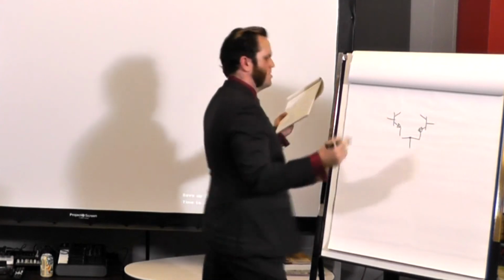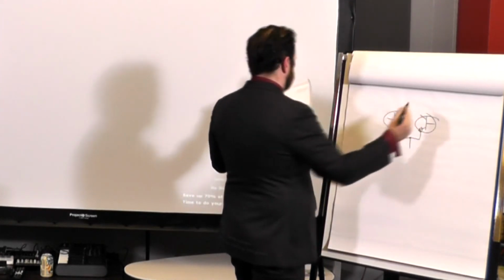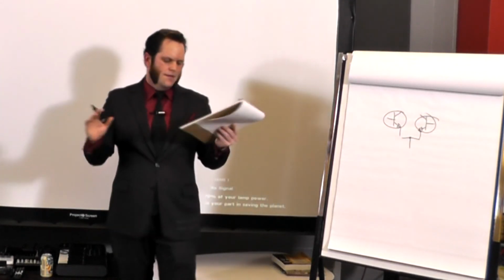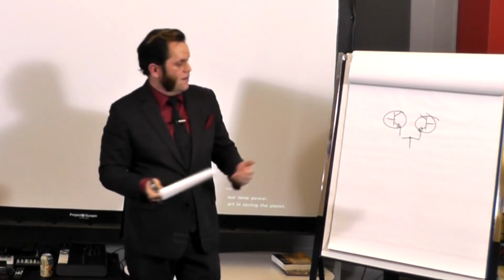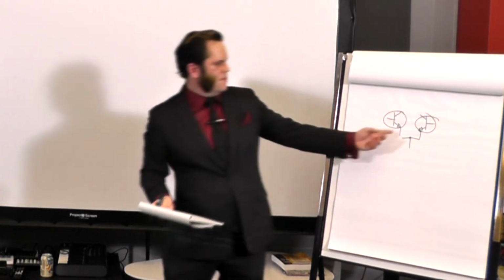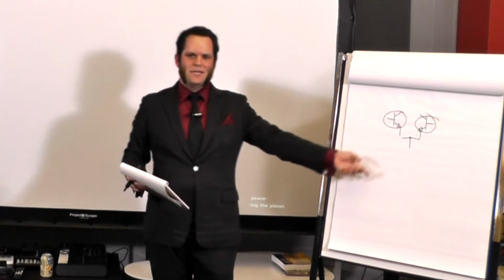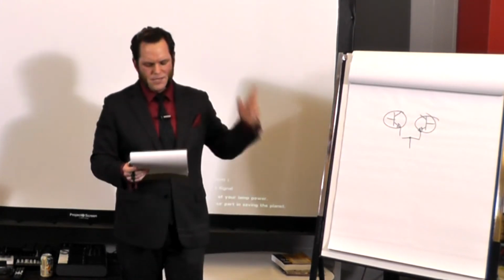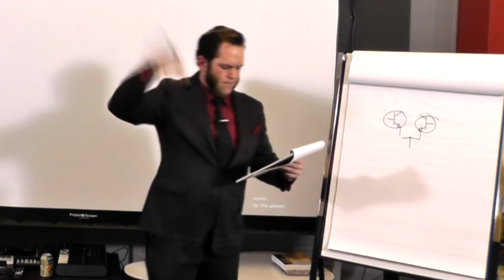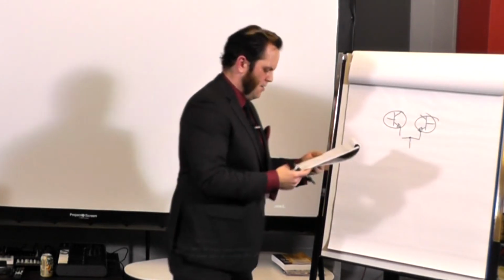Right, so that's the starting structure of a current mirror. And this is going to be really, really useful to us. The premise here is that we've tied the emitters together. If we tie the bases together, the currents going through them are the same because the VBE is the same, and there's math. Magic.